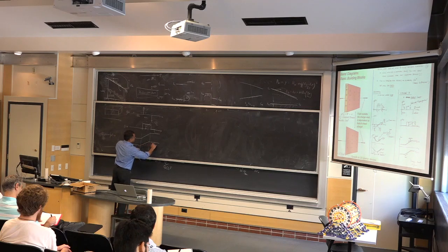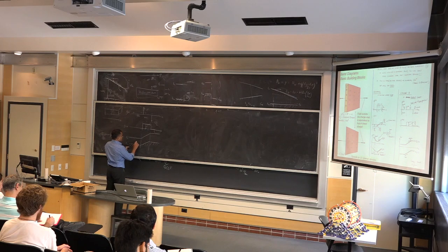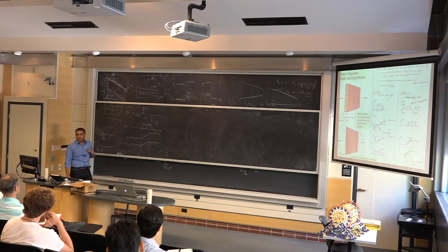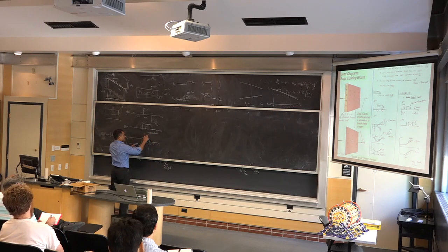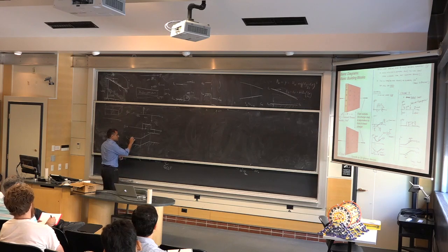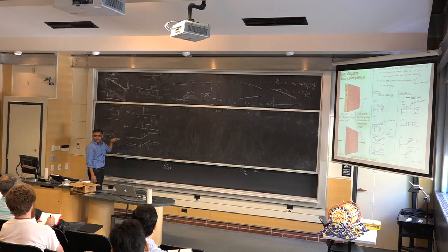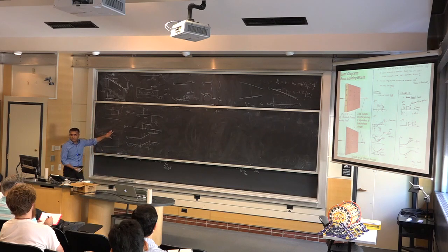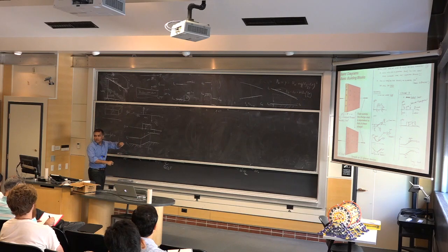But you can see you start building these blocks and say that clearly here, if I shoot electrons that way, this region is going to give them a kick. It's going to speed them up, right? Because it's just like rolling a ball down. You see, it's going to have a little bit of extra kick in the energy if you go that way, right? But if you try to push electrons this way, it's a very hard chance. It's a big barrier. So electrons will not like to flow that way. They will like to flow this way, right? And similarly, holes would love to flow that way because they get a kick as you go around. So this is a barrier. So you can see the directions in which they can flow easily and which is harder for them.